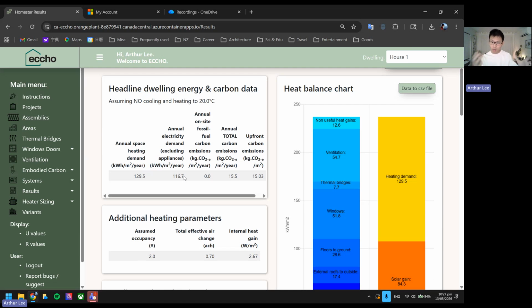It also multiplies by how efficiently we can fulfill those demands. If we try to fulfill the heating demand by using a diesel heater, that's probably not a very efficient example. But on the other hand, if we use a very efficient heat pump that delivers an annual COP of 3.5 on average, that means the heating efficiency is almost 350% compared to, say, a panel heater.